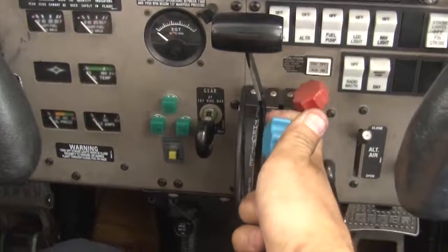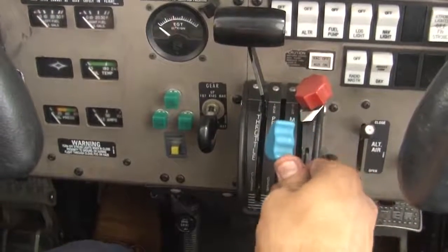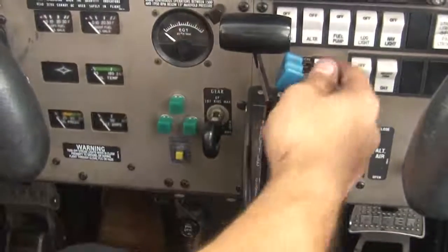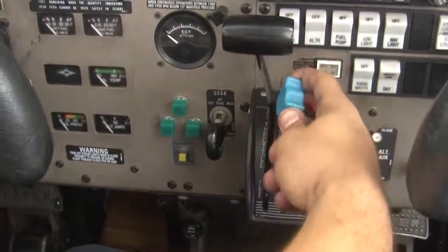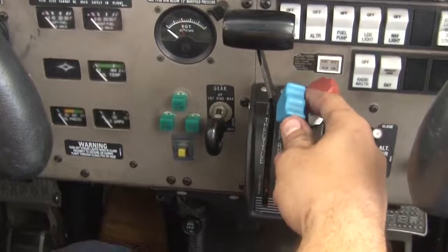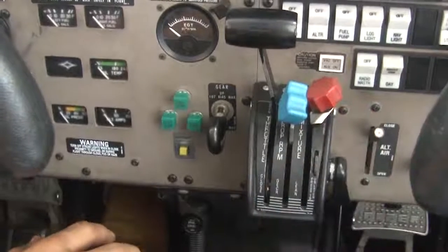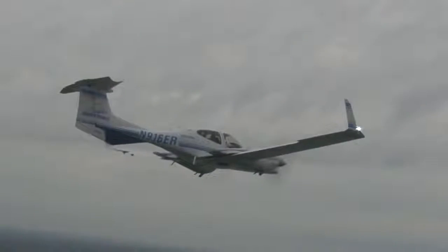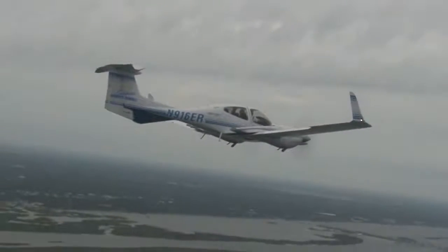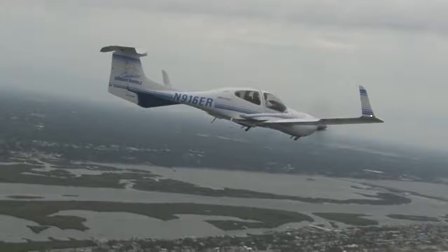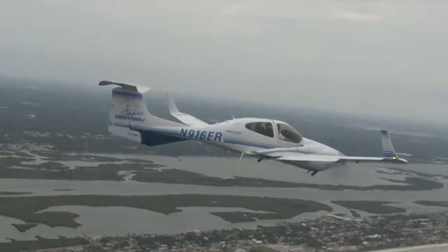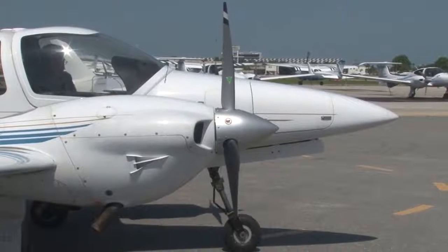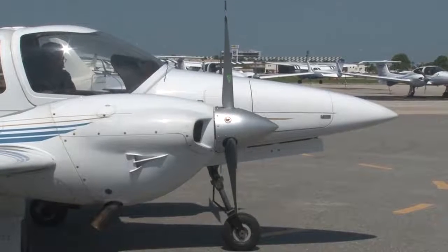Airplanes with a constant speed propeller are not only equipped with a throttle, which still controls the power created by the engine, but they are also equipped with a propeller control. This control, which is usually blue in color, allows the pilot to change the RPM of the propeller instead of just based on the engine's output. The reason this propeller is called constant speed is that when throttle movements are made, the RPM, or speed at which the propeller is rotating, will remain the same. This is accomplished by rotating the angle of the blades, which allows them to deflect different amounts of air.